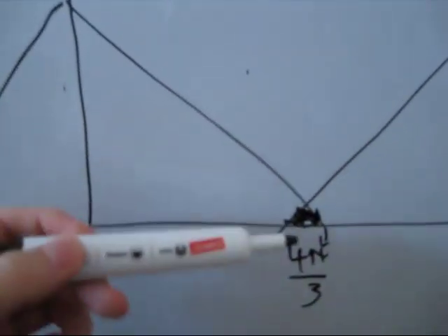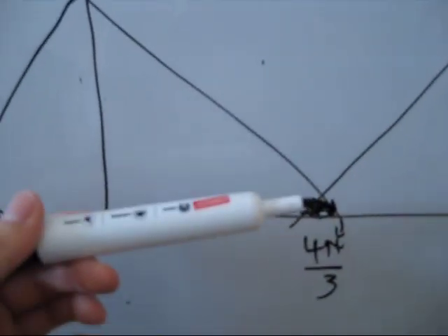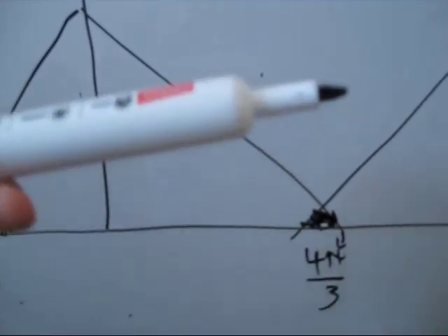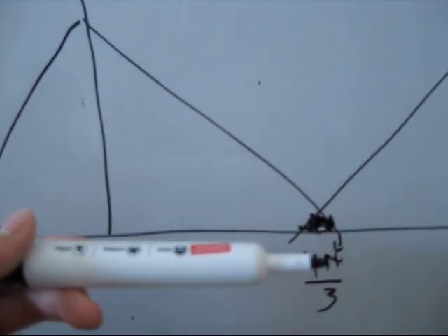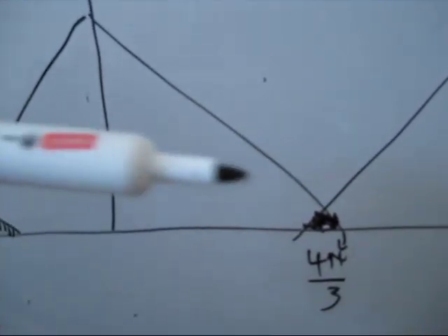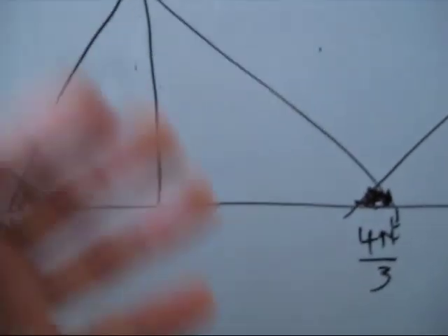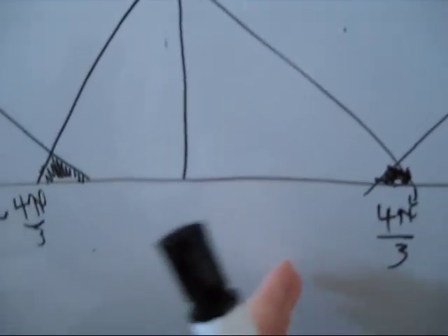So you never want aliasing, right? This is bad. But if we're downsampling this to begin with, our assumption is that what we intend to do is remove the higher frequency components. We don't want them, but we don't just want to do a simple filter, because you do the filter, but you still have those physical data points still there.